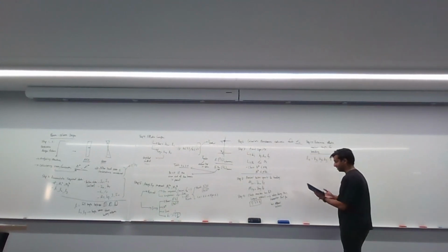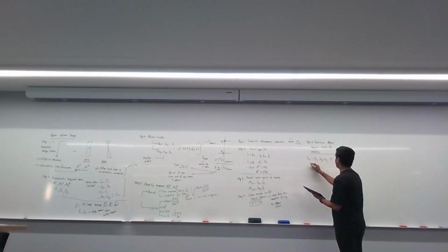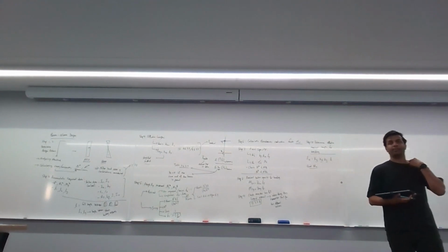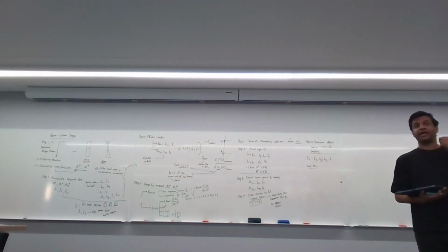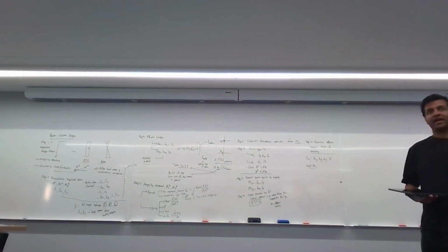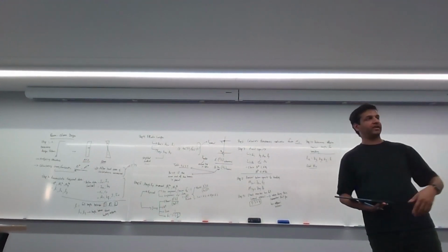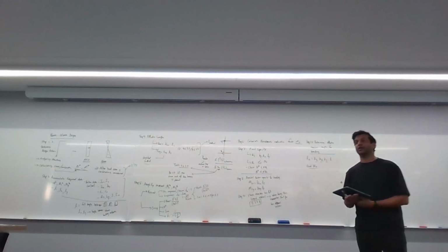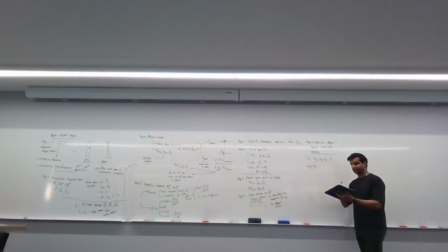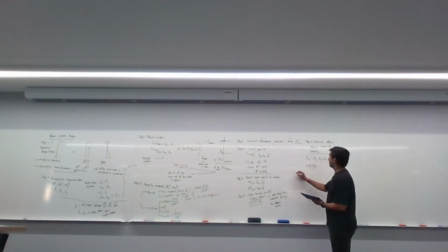Okay? And we need to calculate what M naught is, the reference moment capacity. Now the reference value here, M naught, changes depending on the shape. So if you have an I shape with equal flanges, unequal flanges, etc., they all have different M naught. So just use the correct M naught formula. Again, it's in the code to calculate what that is.